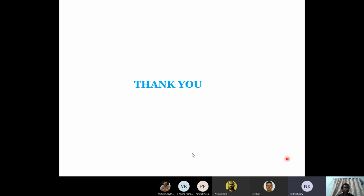This is Nitin here. I have a question. You mentioned policy studies and the transition recommendations you gave regarding decommissioning of thermal power plants. How do you model this? Is there a model based on which you come up with these recommendations? Yes. The total Southern region grid is modeled in the PSSE simulation tool with the help of the Southern Region Load Dispatch Center, where we received the data of all thermal power plants as well as all generation sources, substations, and transmission lines. My team at NIAS modeled the data in the PSSE simulation tool.